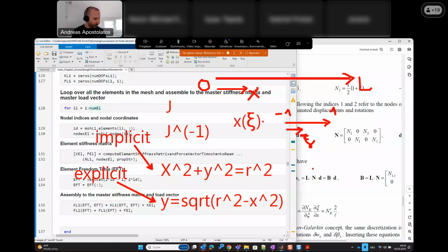All right. So what does the Jacobian show us now? I will just say it in very general terms. I'm not going to be very specific right now. The Jacobian shows us how the local space, the parametric space, bends itself to match the physical space. So it's kind of like a measure of change in the length, if you will, for one-dimensional elements, or the change of the area for two-dimensional elements. That's what the Jacobian is, basically. That's the point for the Jacobian here.